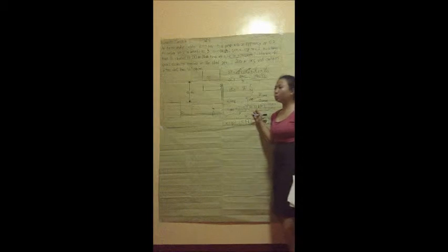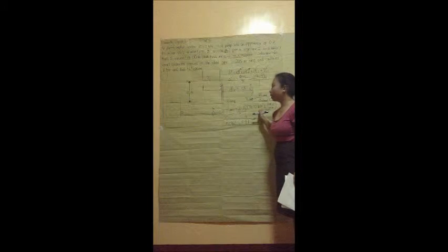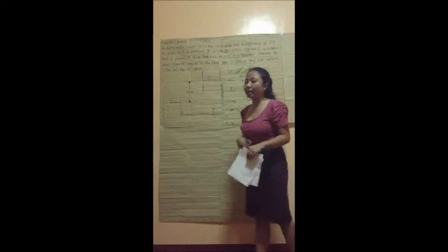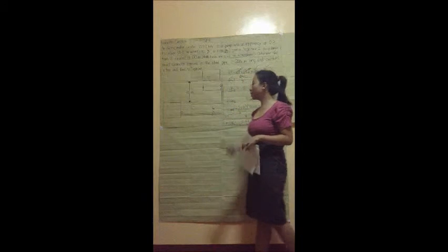But then we have to convert this value into an energy unit, which is joules per kilogram. So first, we use the conversion factor 1000 watts equals 1 kilowatt to convert this into watts. Then we divide the whole value by the mass rate. So how do we get the mass rate? We get the mass rate from the equation m equals volumetric rate times the density.